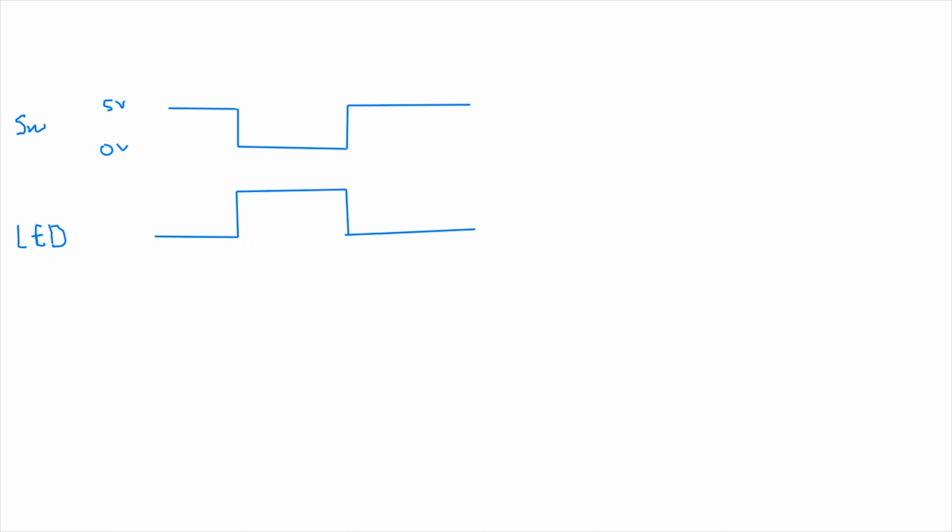We'll look at the screen. So we have a signal coming in, which is the state of the switch or push button. It's always on high, or pulled up, until we press it, then it becomes 0. So we've got a 5 volt signal in, and at the point where we press it, it goes to a low voltage signal. So that's our switch. Then we have our LED. Initially the LED is off, and as soon as we press the switch, it comes on. It stays on until we let go, and then it goes off, or the other LED comes on.